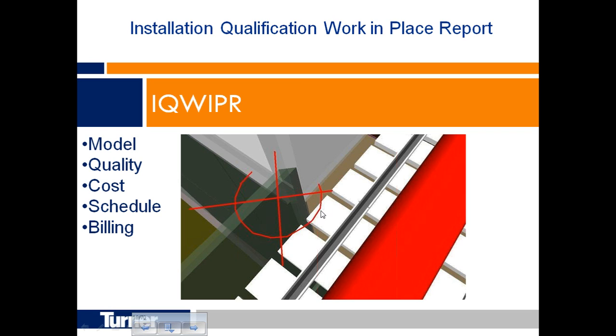This is a wood ceiling where they were looking for as-built information for finished drywall. In this particular case, we shot this before the drywall was on, but knew exactly what the tolerance was. With that information, we were able to release this wood ceiling for fabrication a month and a half earlier than would have normally been possible with normal as-built information.